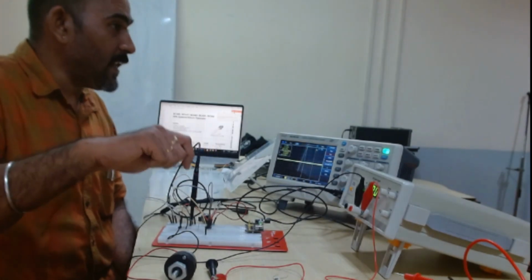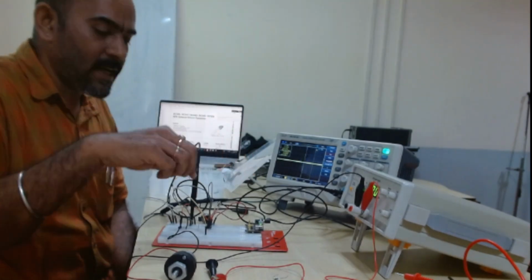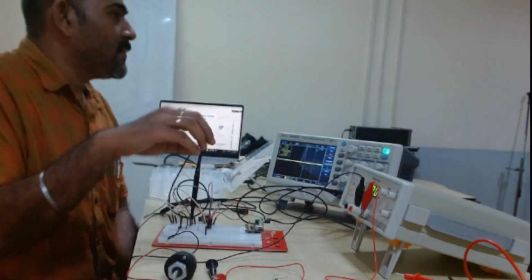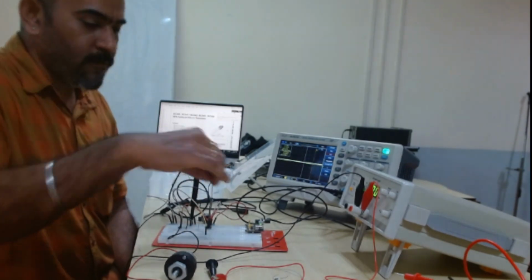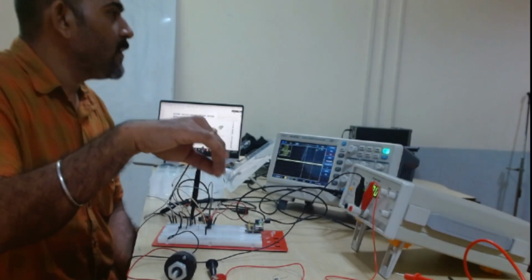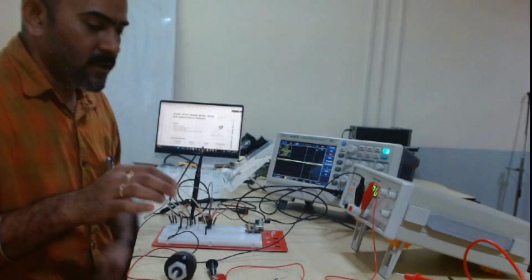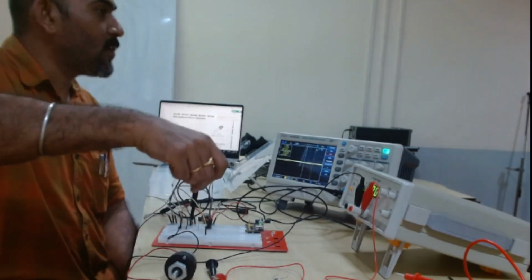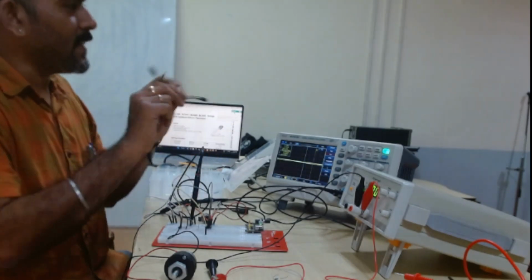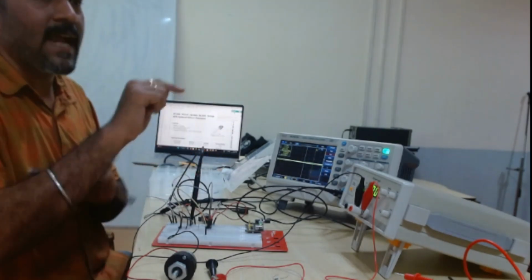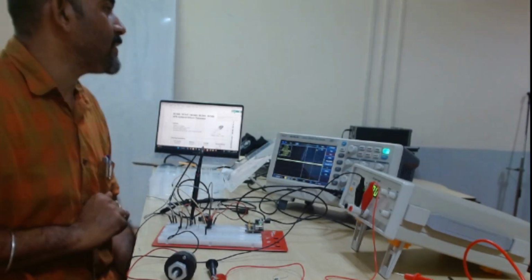Whenever you make the connection, ensure you place the wires appropriately so that you have some room to rework on the component. If you have to remove a certain component, you give enough gap so that you can rework. If you do crisscross wiring, it is always difficult. Even this wire is not apt for the breadboard because the length of the wire is large, so it will look like the wire is coming out. The best thing is, if you have short wires, cut them as much as required and make the connection. That will make the circuit look neat and debugging much simpler.